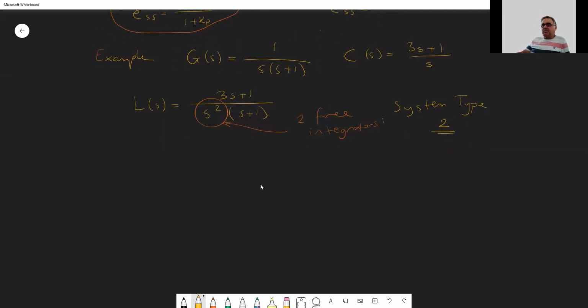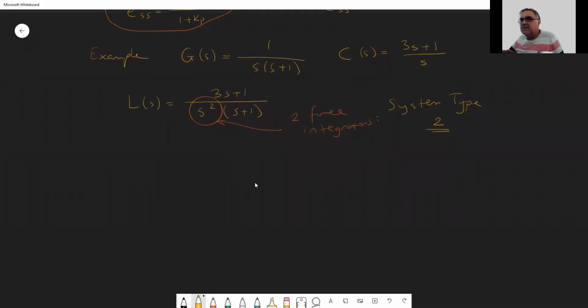So we will now look at the second case, case 2, where you have, remember that we had R and W as inputs. We will have R equals 0, but W of S is not 0, which means that there is disturbance on the system, and we want disturbance rejection from our system. So the two things that a control system must do are good tracking, which is follow R, and secondly, reject the disturbance, that is, the disturbance should be eliminated.